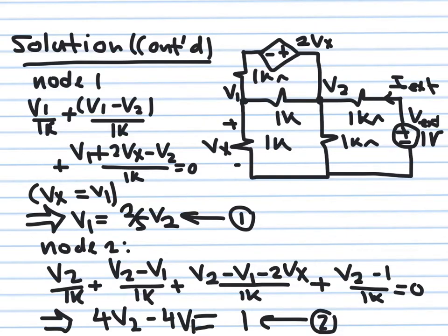And then I applied an external source, and you can see this is the external source I connected in place of the load. This is of 1 volt, and my target is to find the ratio between this 1 volt and the external source current. Okay, so I recommend that you draw the circuit yourself and replace every current source by an open circuit, every voltage source by a short circuit. So when you do that, the equivalent circuit between these two terminals will have only R Thevenin. Okay, because I got rid of V Thevenin. There aren't any independent sources anymore. Okay, so I redrew the circuit, and this is what I end up having.